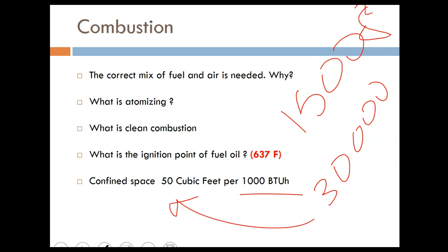And it does happen. It is possible you see a small little basement with the boiler in it, so you're not allowed to enter that place if there is no proper ventilation. You have to go and review the confined space regulation. It has to be off, first of all. It has to be ventilated. And sometimes, if there is no possible way, you might need a breathing apparatus to go with you. And that's the code, and that's for your health. So just bear in mind what's happening about confined space and how you calculate confined space. If you have any questions, please let me know.